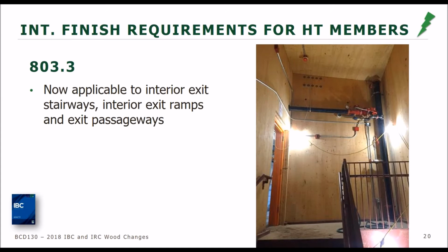So for exit ramps, exit stairways, exit passageways, those exit enclosures, you now have to have even the heavy timber elements comply with the interior finish requirements. It may have been justified when only a small portion of the walls or ceilings were heavy timber, think beams and columns. But with CLT coming into the market more and more, we felt that it was more important to make sure that the interiors of those exit enclosures met the interior finish requirement of the code. Thanks. Great, good background, great background.